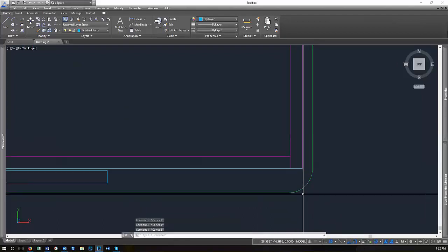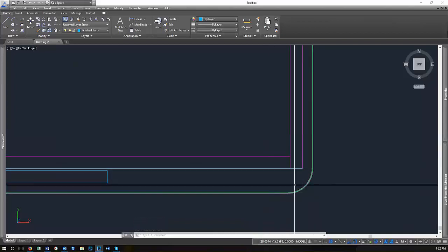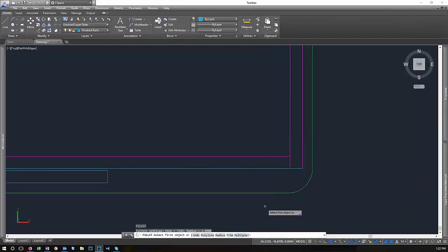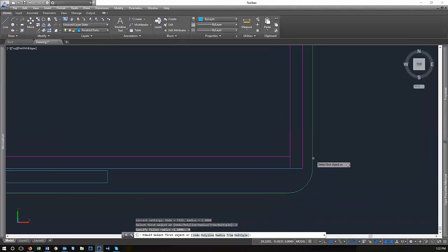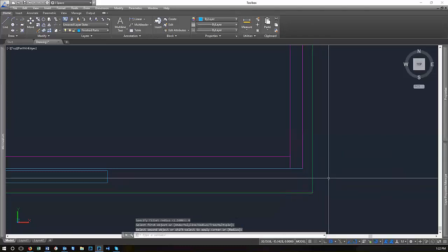Yeah, just got a question about this exactly. So if you have polylines and you fillet the two points, that creates the arc between them. But if you fillet with a 0 radius, previously with the regular lines, I ended up with an extra arc here. But if you fillet between 2 points on a polyline, it will eliminate that arc as well.